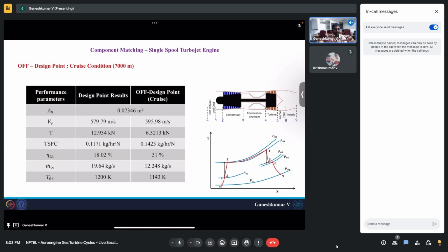Okay, and you will end up having a bunch of equations, and you solve all these equations for different operating conditions, and you will end up drawing engine operating lines as a separate graph, and that will be used in order to maneuver your flight. Okay, that is actually coded in the electronic control unit, the ECU of your aircraft engines. Okay, so this is the logic behind.